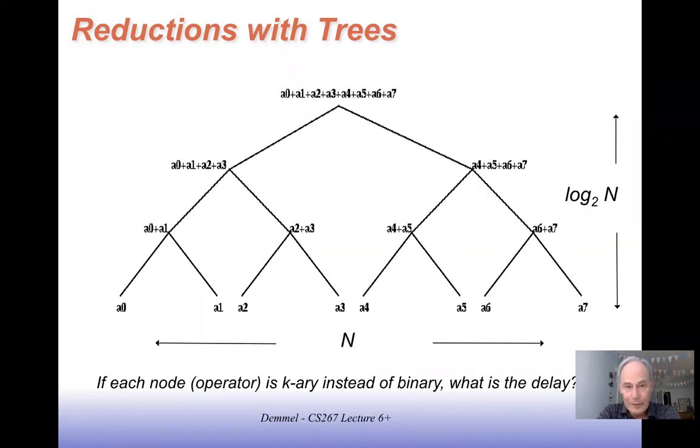And we talked about the fact that we like trees when we do hardware design, when we do reduction type operations, or really computing any function. If we can find a way to do it in a tree form, then the delay should be proportional to the log of the number of inputs. Right? And that's a really nice property to have, because if you look at adders, for instance, in a CPU these days, which are 64-bit wide CPUs, meaning the operands, the registers are 64 bits wide.